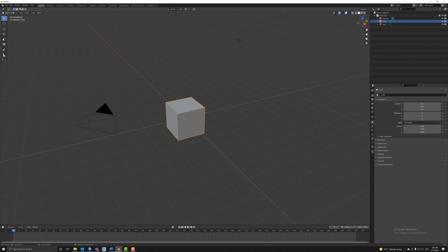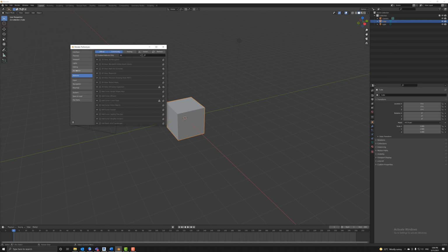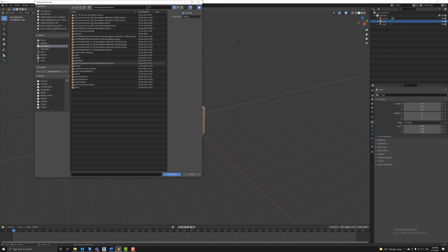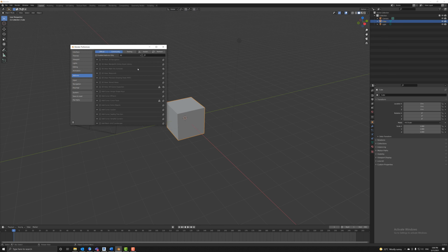The next thing you're going to want to do is go into Blender and enable that plugin. To do that, you just go to Edit, Preferences. You'll go down here to Add-ons and click Install. Now, I've already got it installed, but you just go and click on the .zip file, the Maps Model Importer zip file. Once you've done that, it will be visible in the list here. See, Export Maps Model Importer. So that's downloaded and installed.